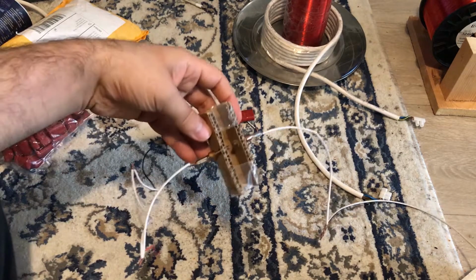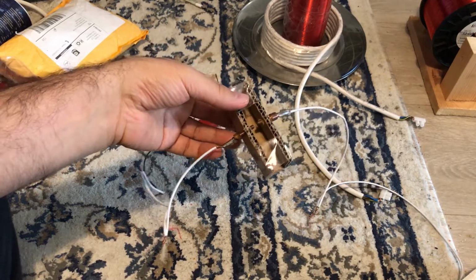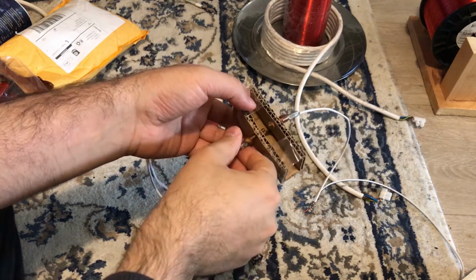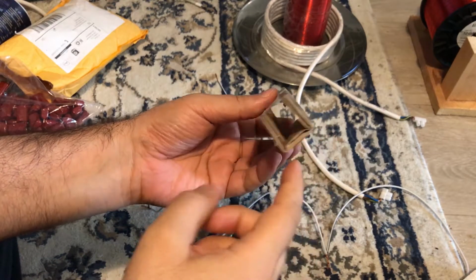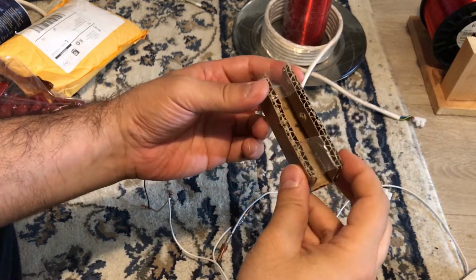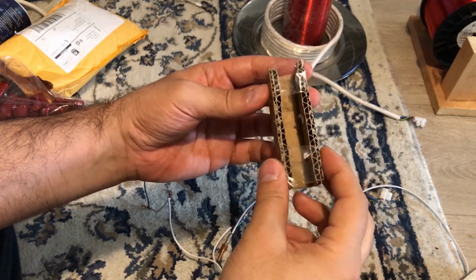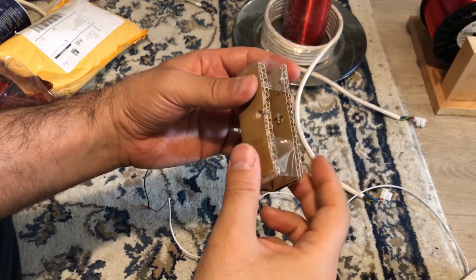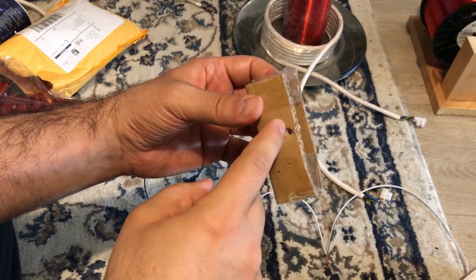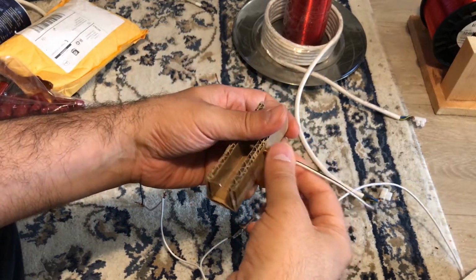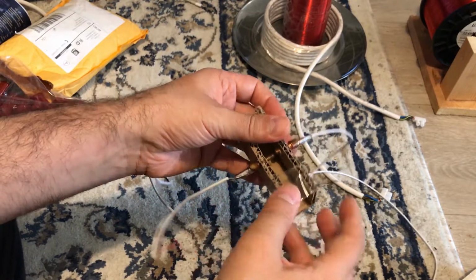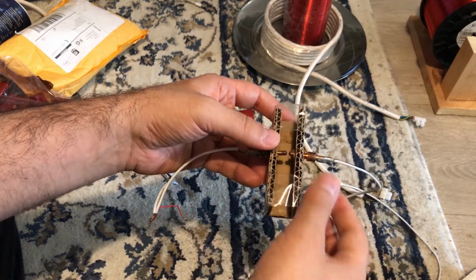Another very important part is the spark gap. In this case, I use a stationary spark gap. Basically, I took a piece of cardboard, I created a bend here, and then put some packaging tape on these sides. So now we have the structure, and I created two holes. Basically we can put the electrodes inside and this will form the spark gap.